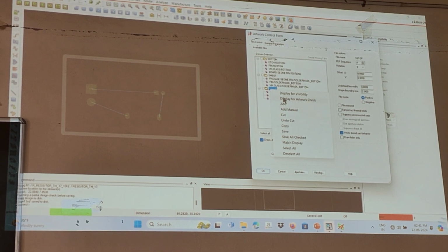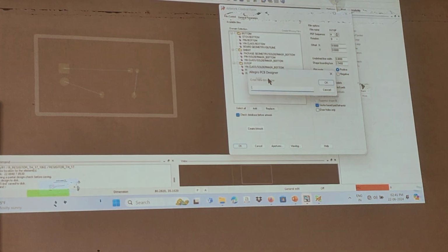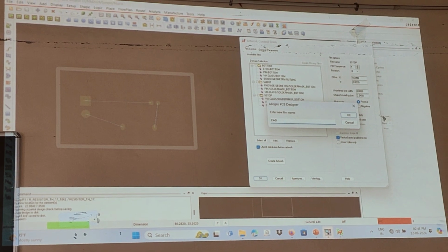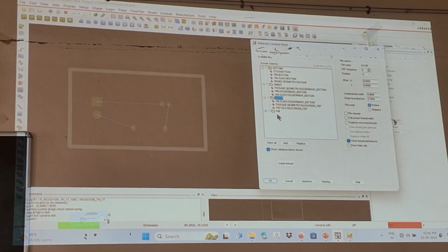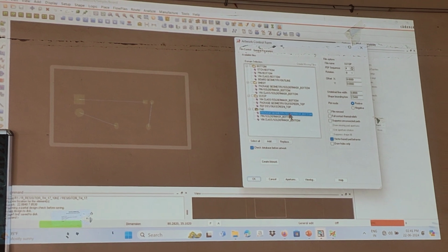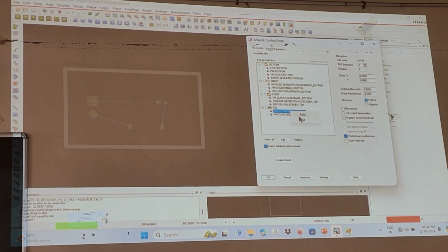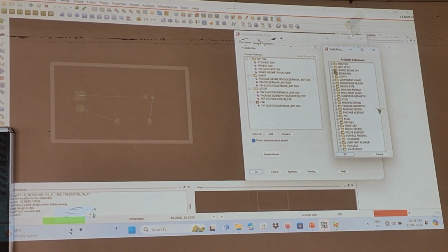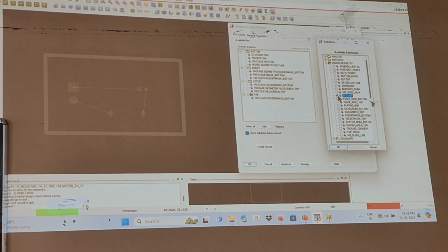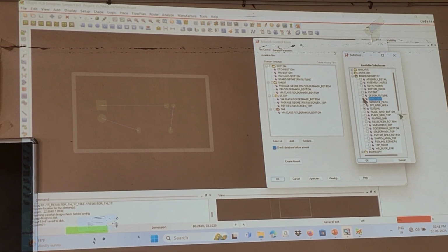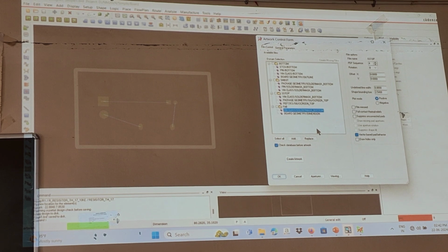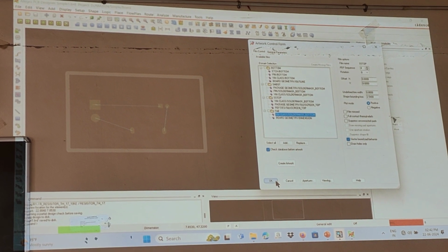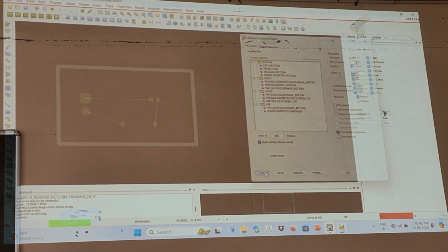And next we need another layer called fab. Right click and view, select, create the film of fabrication layer. Click OK. Then we need board geometry, outline, and board geometry dimension. Then click OK. We have created the 4 layers for the single layer PCB. Then click OK.